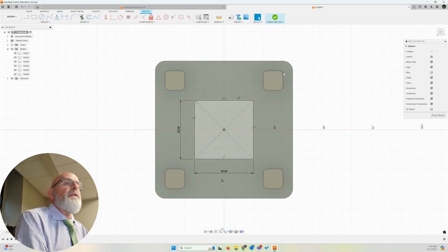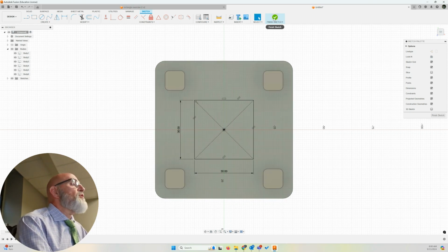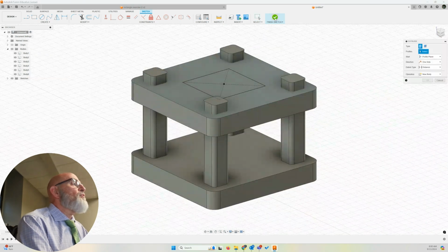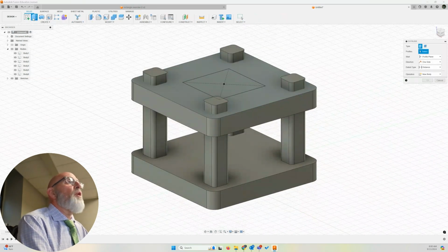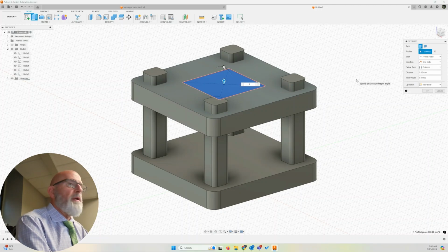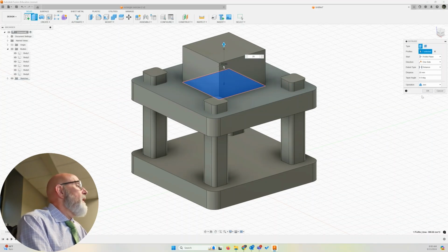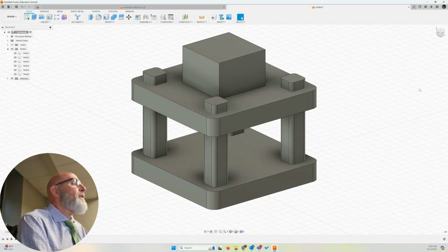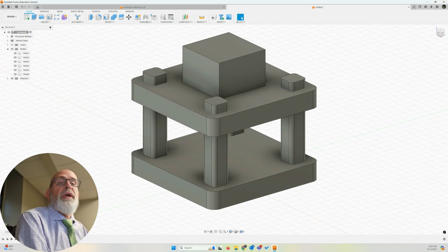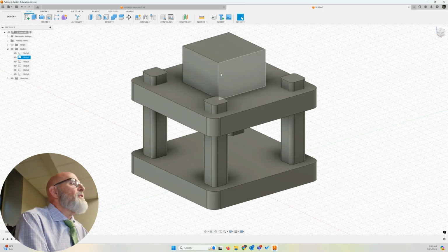All right. Let's extrude it as a new body. So let's finish sketch. Extrude. So I hit E on the keyboard. Create extrude, 20 millimeters. Click OK. Now, as I said earlier, since it's a center rectangle, I do the fillet that we're going to add, which is a 5mm fillet on these edges.